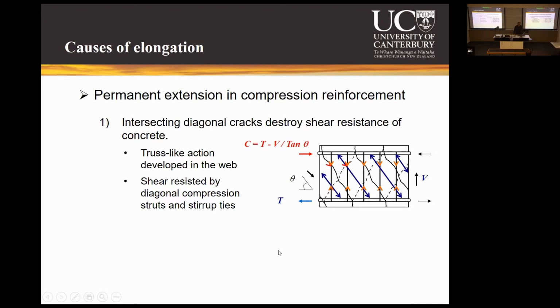And now let's look at this in a slightly different way. Let's look at the two bars, the bars at the top and at the bottom, right? So that is your equilibrium here. A bar which was in compression in the previous cycle now gradually goes into tension and strain hardening, because it needs to develop much larger force than what the compression bars need to develop, right?